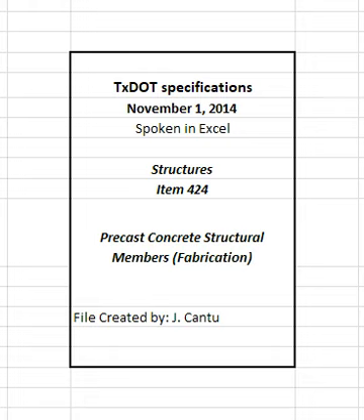Anchor internal void forms to prevent movement or misalignment while placing concrete. Provide hold-down devices for all types of void forms at 30 inches maximum spacing unless otherwise approved. Do not use internal hold-down or lateral bracing devices that will remain in the finished member unless approved. Provide enough bearing area on the void form to prevent penetration of hold-down devices into the void form.